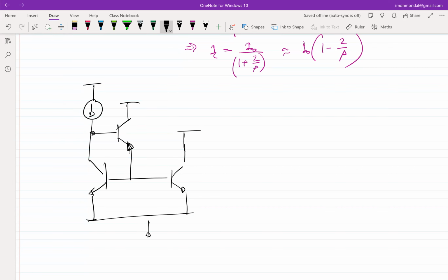And note that in the case of a MOSFET, if you had done something like this anywhere, you had to put some current source here in order to provide the biasing current. But in this case, we are using this extra transistor because there is already a current, and we want to ensure that the current is not loading the previous stage. So essentially, you don't have to put anything. This will auto bias.